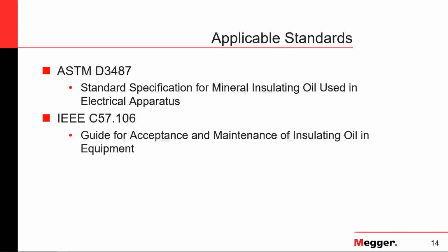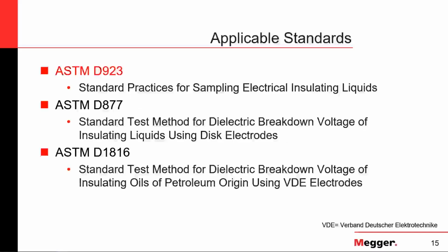Both the IEEE standard that I mentioned before, IEEE C57.106, and standard ASTM D3487 will give us guidelines in regards to the actual limits, or the minimum breakdown voltages we need to verify, depending on the application we are taking our samples from.